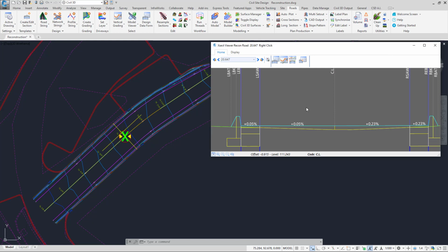So in summary, the road widening project will position the centerline of your string onto the sampled surface with a thickness value of your choosing. It will assign that thickness value to your saw cut, position those also onto the sampled surface, and then create strings left and right, depending on your design, which will be a projection of the slope from the centerline to the saw cut.